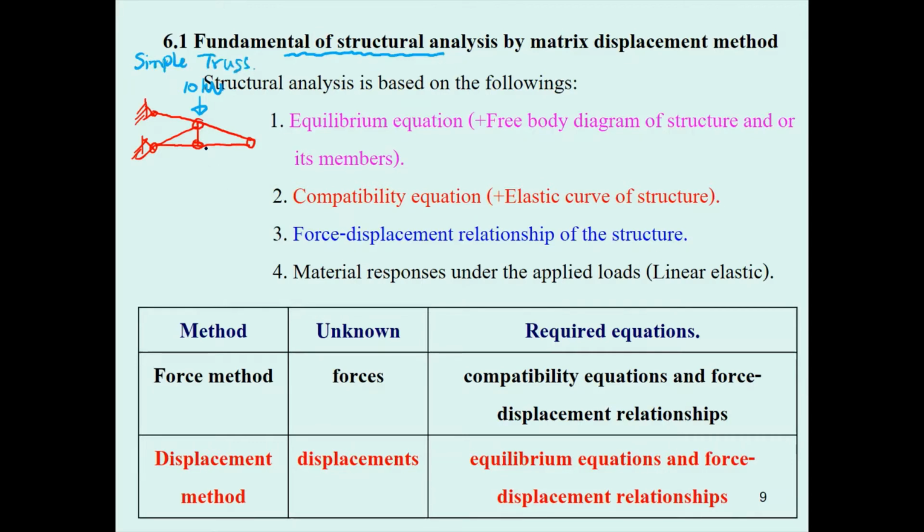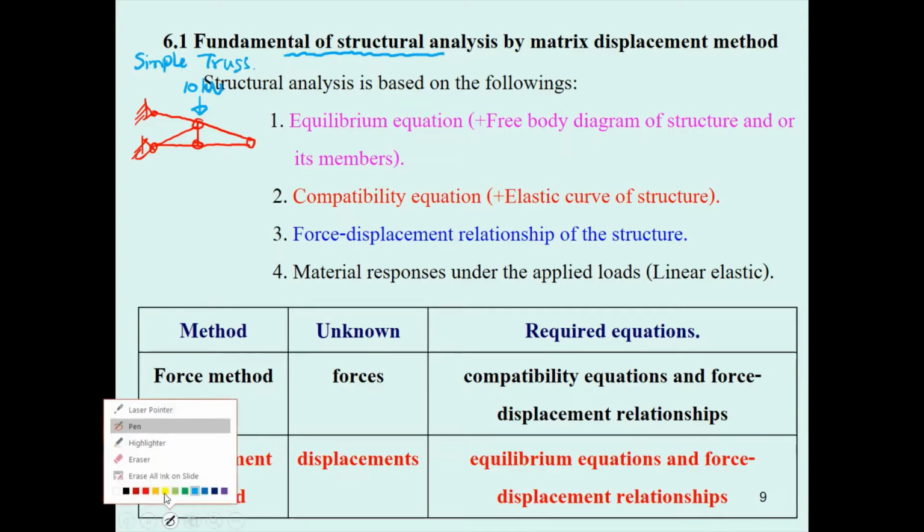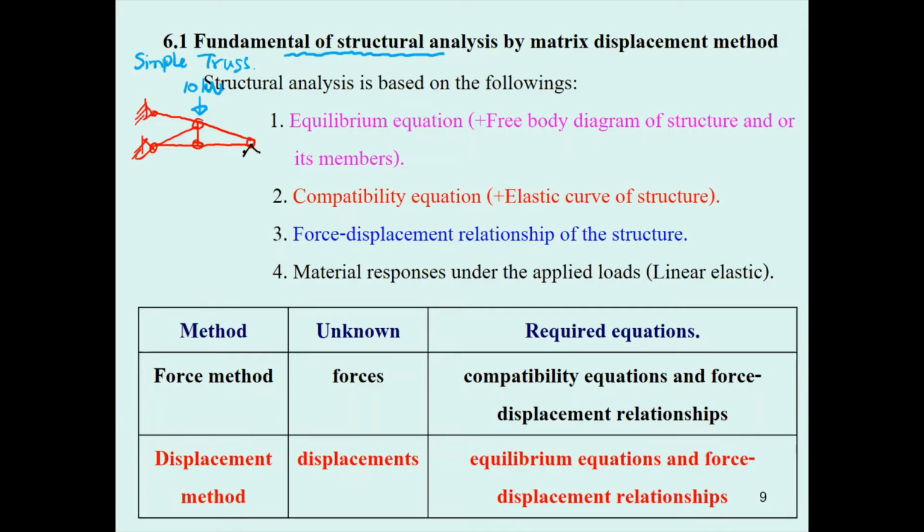And later, after you use this truss for a while, the requirement of the truss may change. Okay, you may put a support such as a column to support this truss to make it stronger, to make it stiffer, or more stiff, or to resist larger forces by putting in more support. This changes the statically determinate truss into a statically indeterminate truss with 1 degree of indeterminacy.